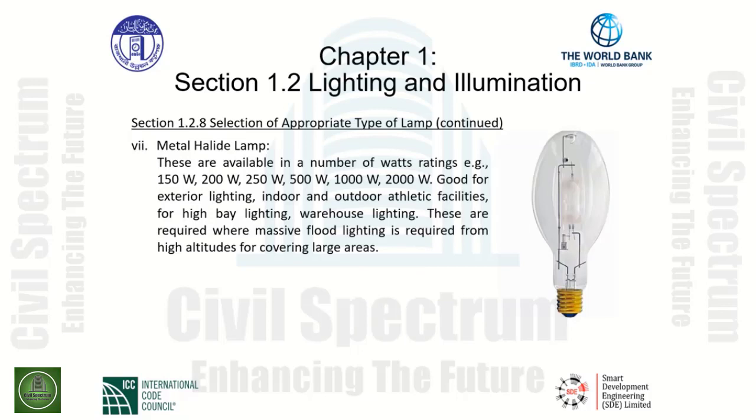Metal halide lamp indicated in item 7 of section 1.2.8. These types of lamps produce an electrical arc between two electrodes in an atmosphere of argon, mercury, and metal halides, which are produced by combining halogen with a metal. These are available in a number of watt ratings. For example, 150 watt, 200 watt, 250 watt, 500 watt, 1000 watts, and 2000 watts.